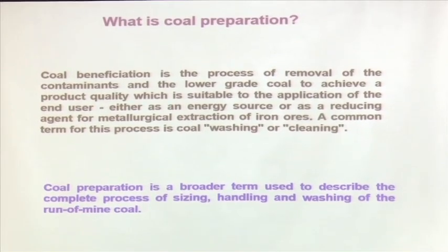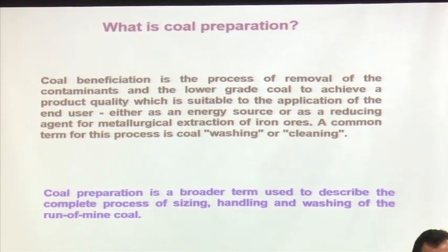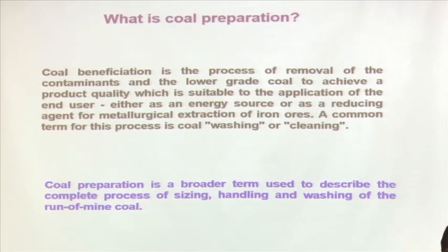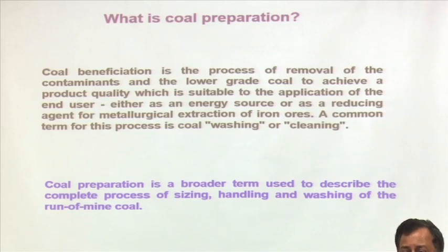Many times I may not need to wash the coal or upgrade the quality, but I need to conform to the quality related to size distribution. So, I need only to do sizing. When I am doing only sizing, that is breaking the coal by a crusher and controlling the size distribution, that is also part of coal preparation. So, coal preparation is a broader term where coal washing is one part of that.